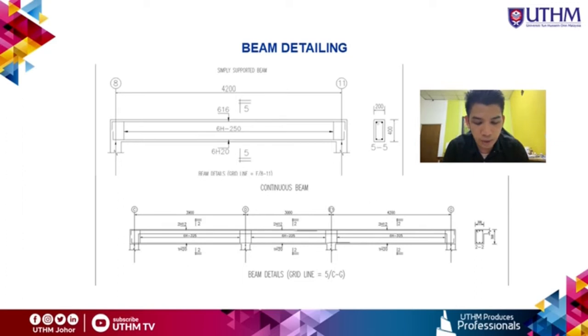As for the detailing, the reinforcement required is H16 and H20 for the tension and compression zones, and the link reinforcement is at 250 mm spacing, center to center.